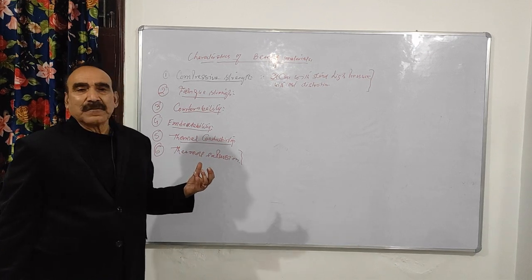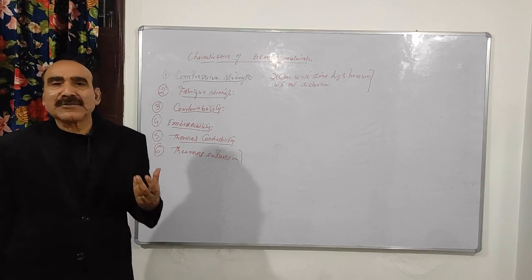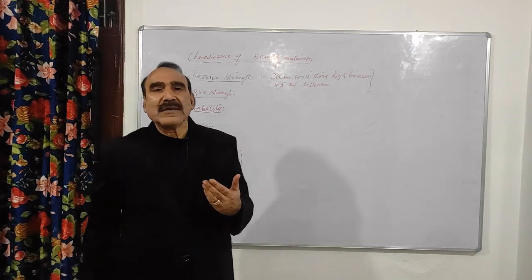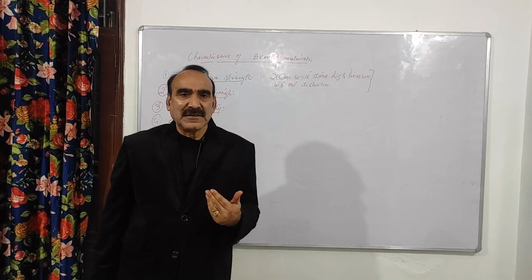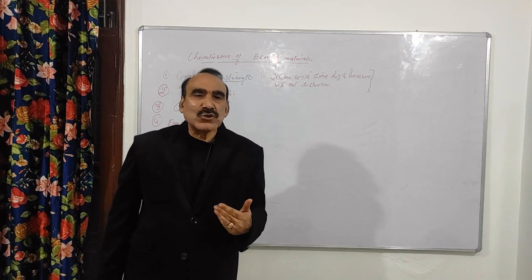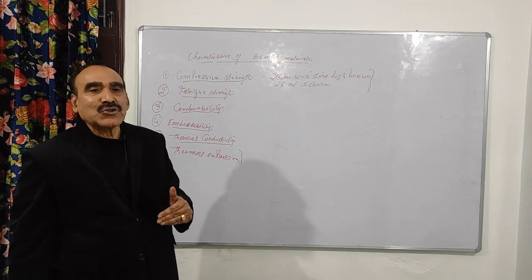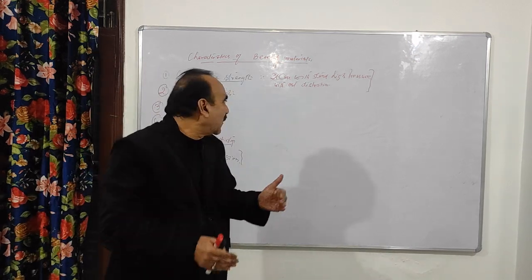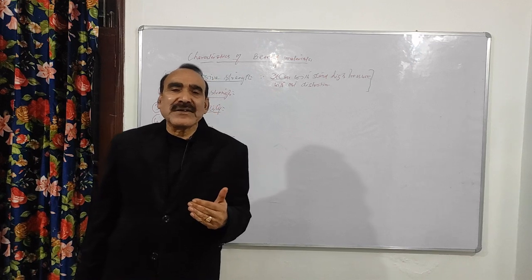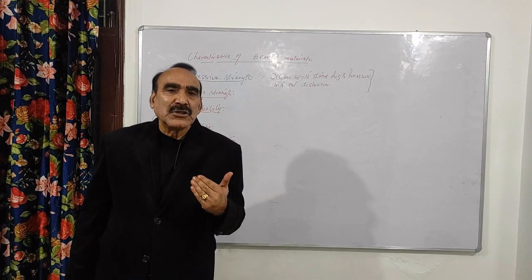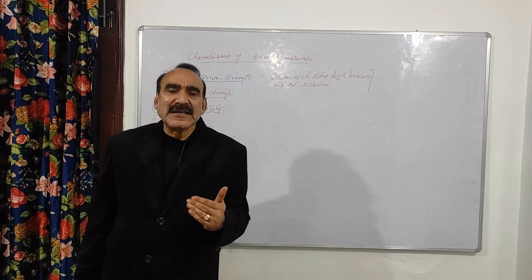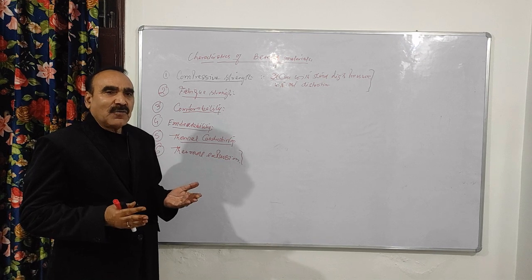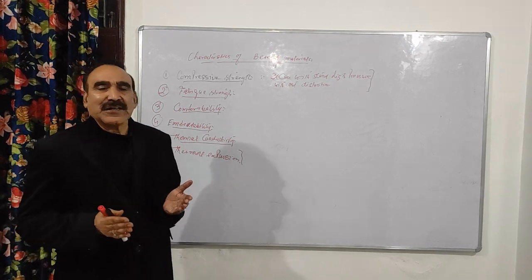It should have a low thermal expansion, so that due to heat generation there is no deformation, no expansion of the material, and the gap between the bearing surface and the journal surface is minimized. So thermal expansion should be low, so that the expansion due to heat generation is as little as possible, right?